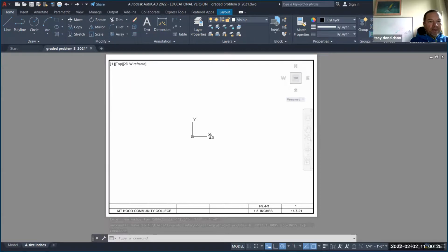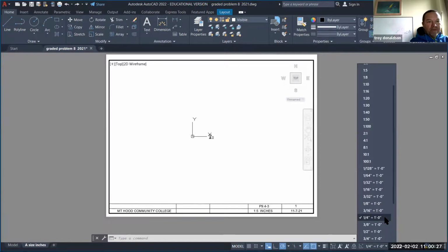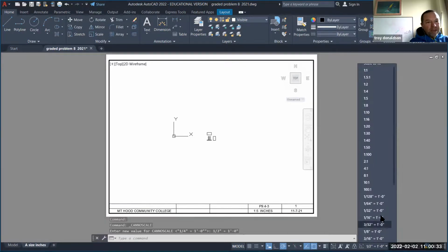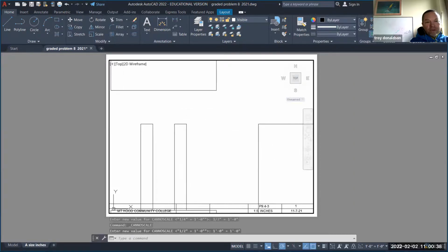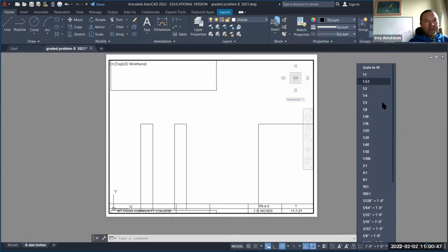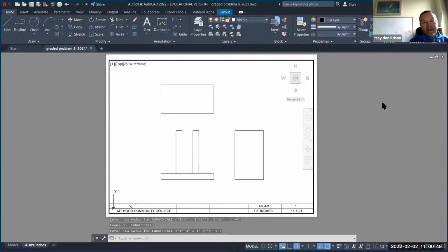So that means that I need something much bigger, like 1/2 inch to a foot, or maybe 1 foot, right, to 1 foot. Nope, not that. It's close though. And the other scale is the engineering scale, which we can do. Maybe I'll just choose half scale, right? So depending on the type of scale you want, how you want it to read, half scale looks pretty good.